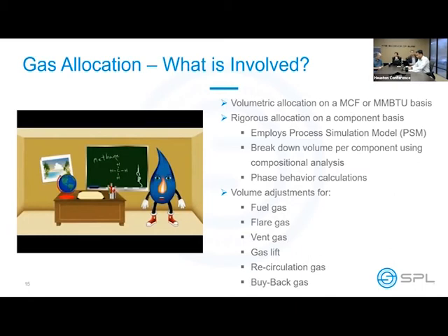Gas lift is what always makes me think of it. More often than not, you're not getting good pulsation dampening coming off of that gas lift compressor, and it's throwing off your measurements of your gas lift. So now that's in error, and that error just reverberates through your allocation all the way down the system, as will any error. So it's all a balance of good, accurate measurement and analysis fed into that model.